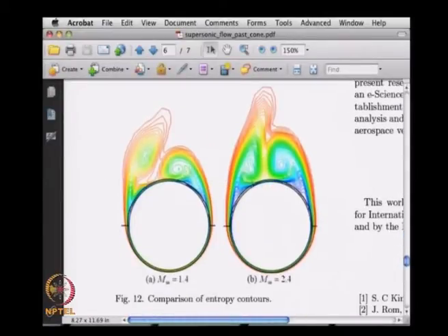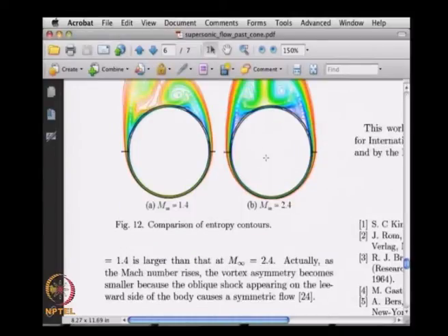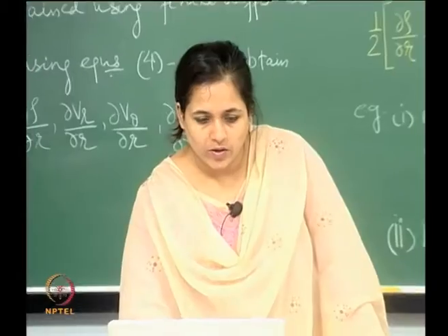And this is yet another one. We looked at the change in the length. Now we will look at what happens if we change the incoming Mach number. You can see the same large changes in entropy if we change the Mach number from 1.4 to 2.4. Even that is quite an important change here. I think we will end on that note.